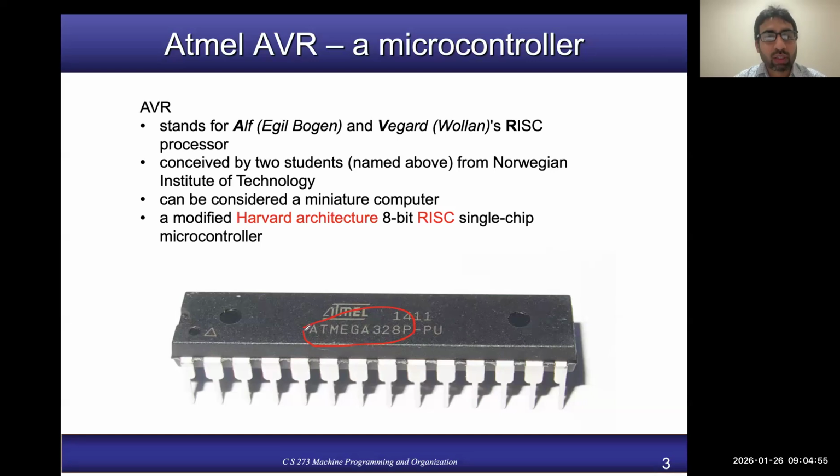And this microcontroller is 8-bit. When we say 8-bit, it means that all microcontrollers or processors have internal registers. Registers are nothing but data holders. Data can reside in memory, but when the CPU needs to access that data, it is first placed in the registers. Why in registers?